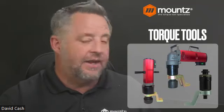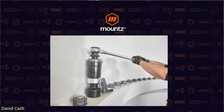And so if we take a look at an example of a hand multiplier that's in use, this could be like an 8-to-1 type of multiplier. So if we put 200 foot-pounds on the input and we're at 8-to-1, then we're getting 1,600 foot-pounds as the output.